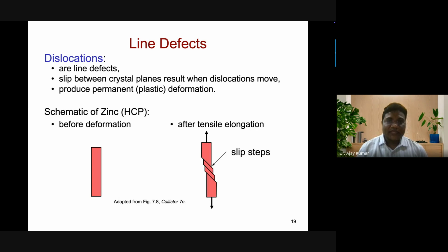One definition: if you apply a load on the material, like you do in the universal tensile testing machine, then it has elastic deformation, as well as, after the yield point, plastic deformation, right? So when you release the load within the elastic limit, the material will come back to its position. You say elastic deformation. If it doesn't come back, then you say it is plastic deformation, right?